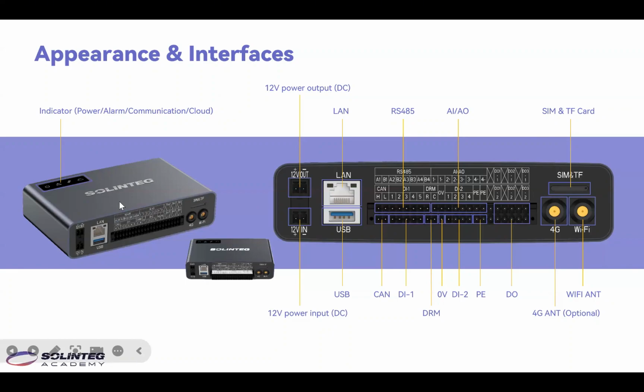The shell is made of aluminum, with extrusion molding as the process, and the surface has been treated by anodizing, so it has excellent corrosion resistance and surface smoothness, long-term durability, lightweight construction, and high heat dissipation capability.